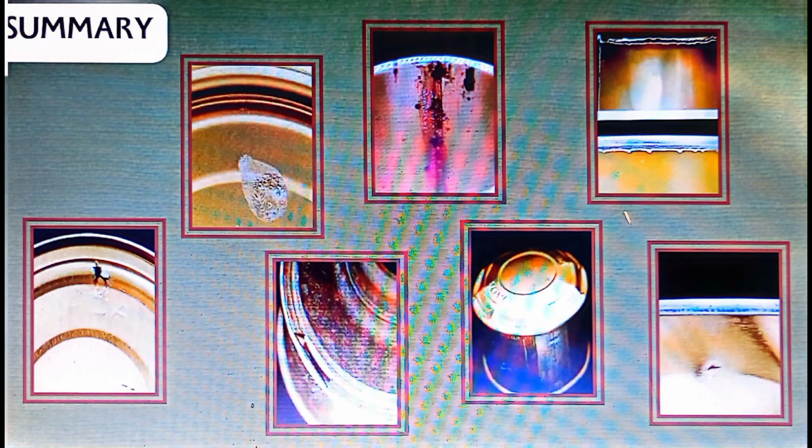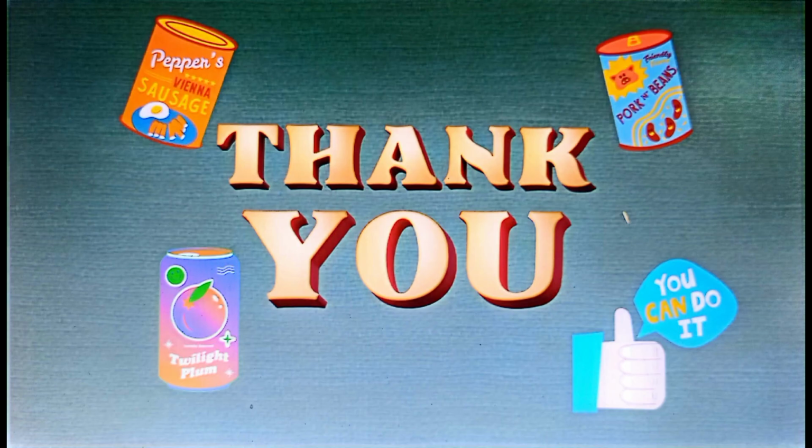In summary, this video discusses the seven metal can defects by choosing one sample from each category, such as the pinhole, coating drip, flux stains, double ends, broken chuck, overfill, flipper, springer, as well as, lastly, the punctured can. Their classification, description, and common sources may enhance our knowledge in terms of identifying kinds of metal can defects.